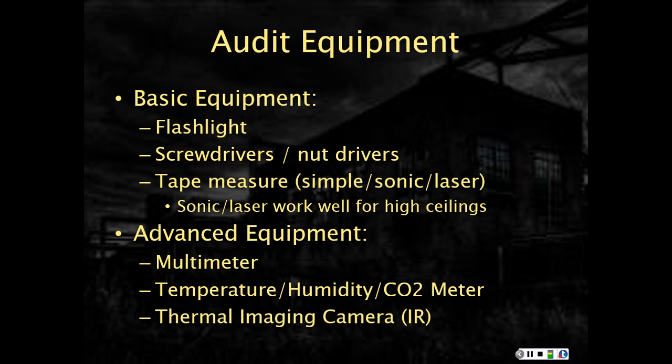In recent years, the pricing on these have come down considerably. You can now get thermal imaging cameras that actually pop into the bottom of your smartphone. They run about $300. These come in very handy to look at windows, doors, walls, check for differential temperatures happening in places. You can even detect moisture getting in under different areas. You can look at electrical boxes and see hot spots. Thermal imaging cameras really become a valuable tool in doing energy audits.